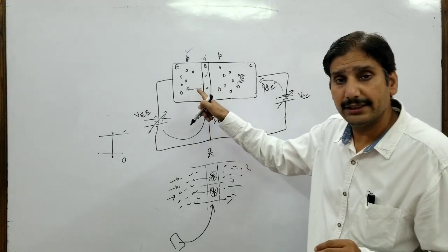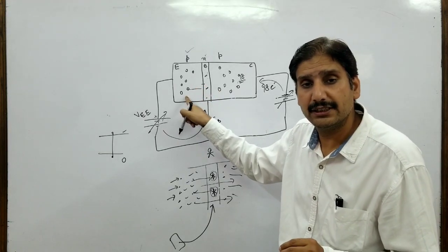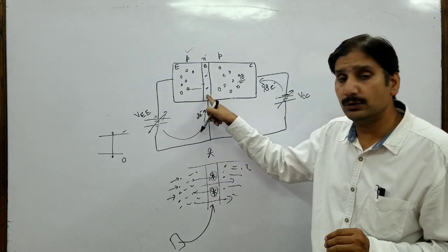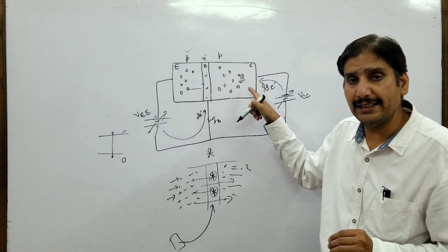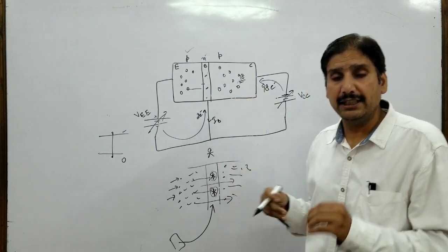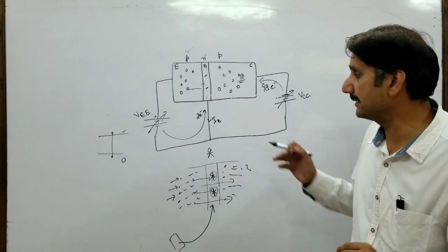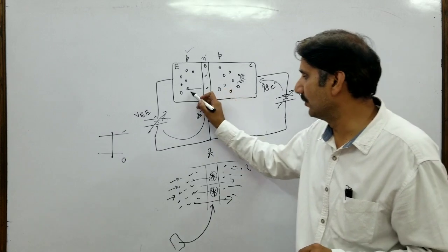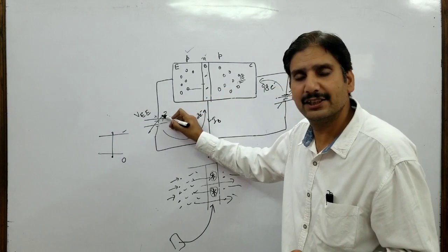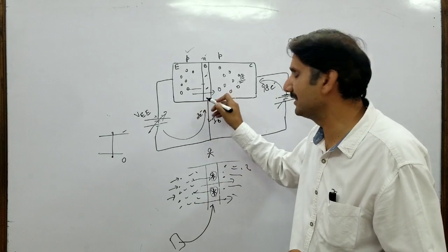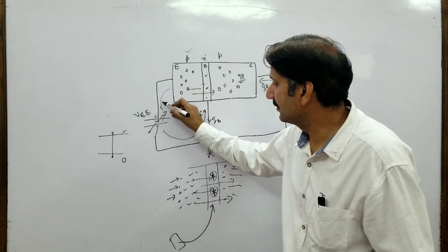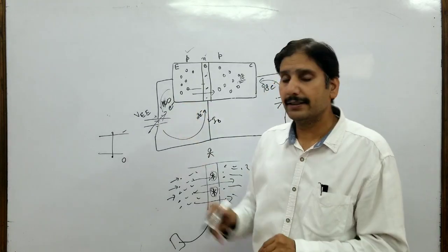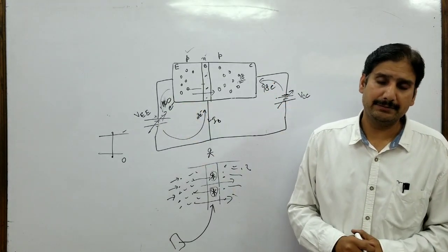Now, 100 electrons and 100 holes have been generated in the emitter region because 2 neutralizations took place in the base region and 98 neutralizations took place in the collector region. So a total of 100 neutralizations have taken place, so 100 new covalent bonds break in the emitter region. These 100 holes are again pushed by the positive of the VEE battery across the junction, and the 100 electrons are attracted by the positive of the VEE battery.